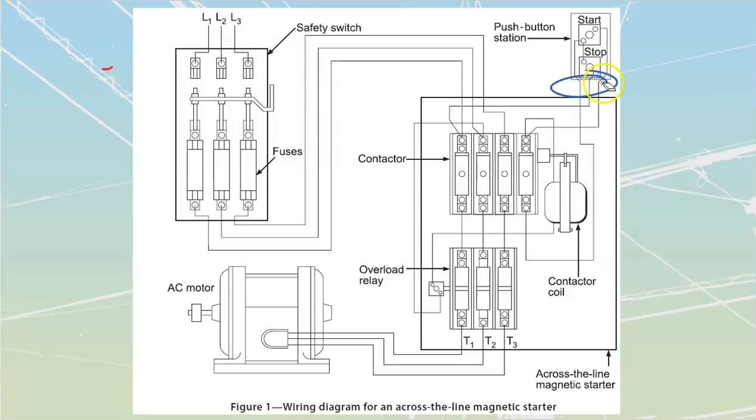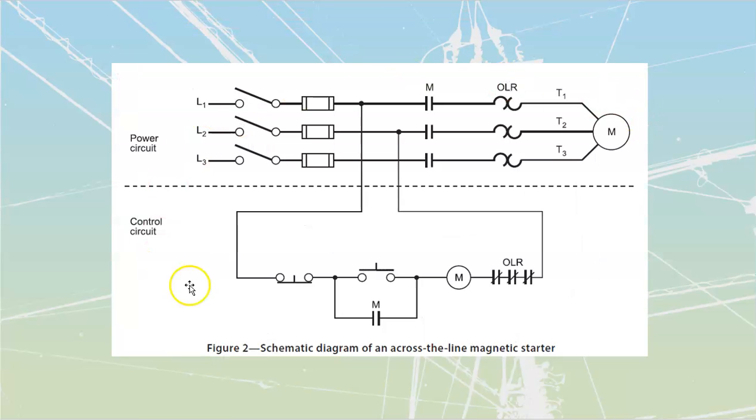So I've got my 3 wires up there, and I can identify which terminals I'm going to put them onto. My start button is going to have 2 terminals. My stop button is going to have 2 terminals as well. And then I can figure out what the other sides go to inside of each of these. Really easy ways for us to troubleshoot and get there. It is a tough drawing to make though, because we get pretty decent at making this.